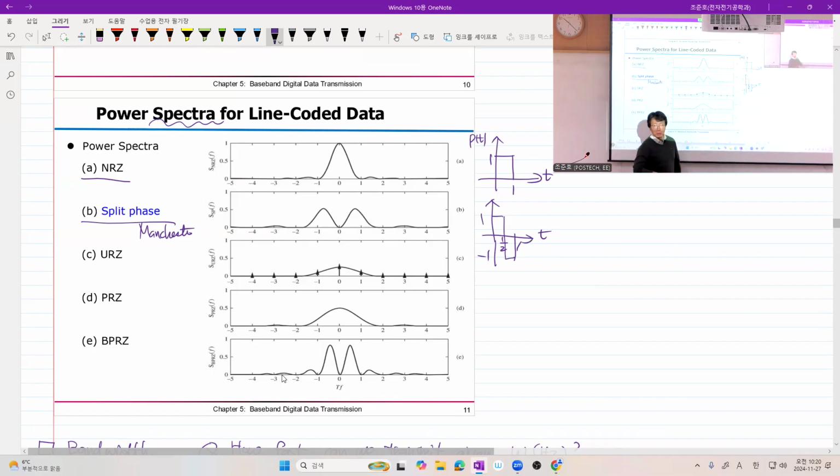Compared to the pulse shape of the non-return to zero line encoder, in the Manchester code, you have 0, 0, 0, so far the same, 1, so far the same, 1, 1, but a sudden drop to negative 1 and a sudden up to 0. So your intuition from signals and systems says that the pulse shape for Manchester code has much higher frequency components than the NRZ case.